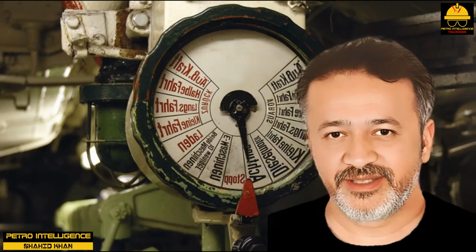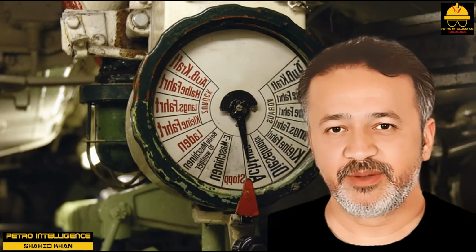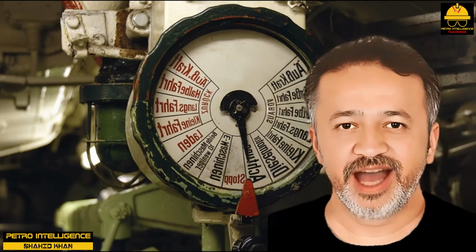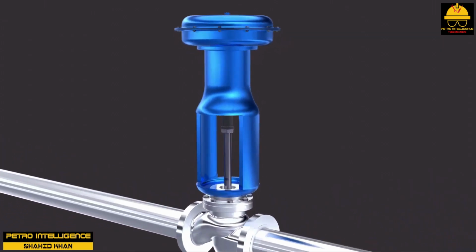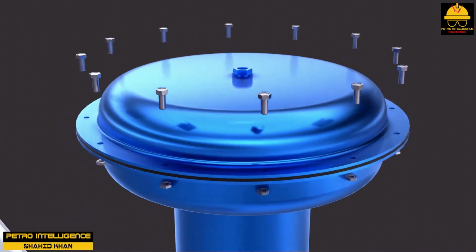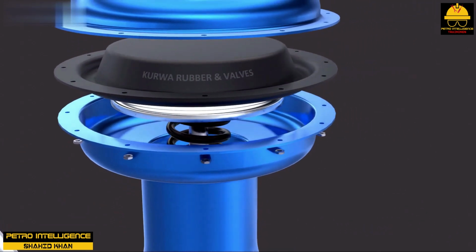An actuator is the device that automates a valve. The actuator controls the position of the flow control element by moving and controlling the position of the valve stem. Actuators come in three basic designs: pneumatic, electric, and hydraulic. Pneumatic or air-operated actuators are the most common. Pneumatic actuators convert air pressure to mechanical energy. They can be found in three designs: diaphragm, piston, and vane.